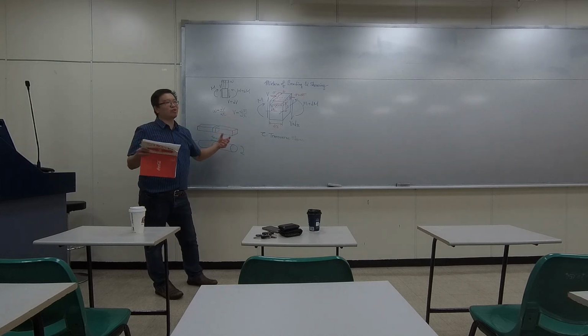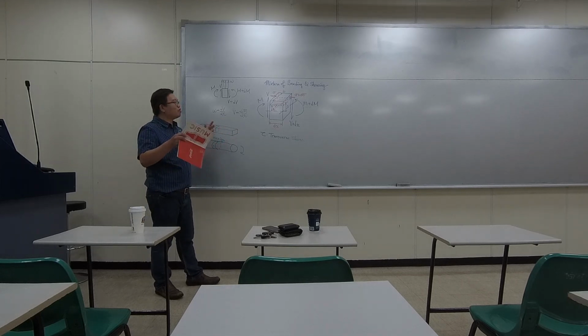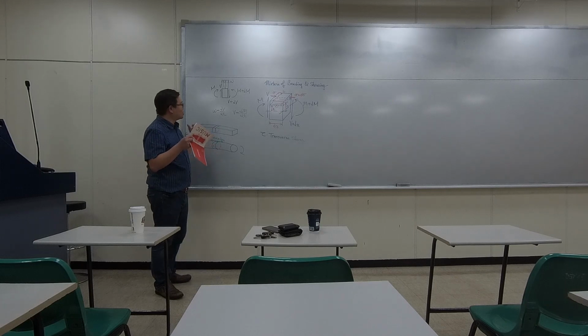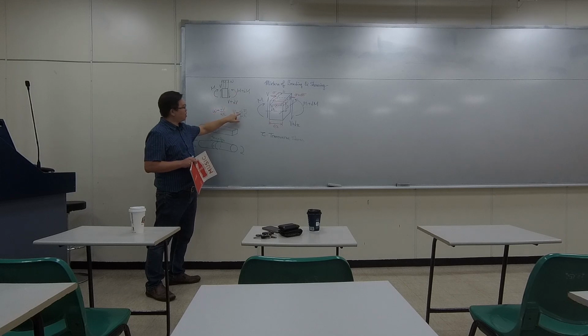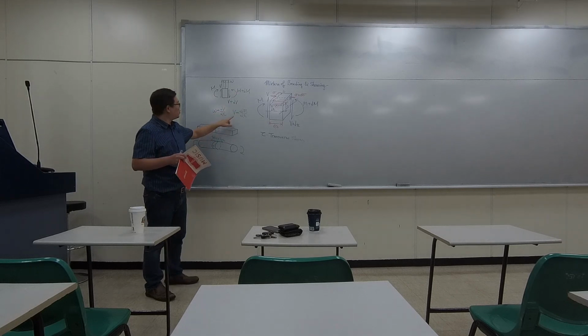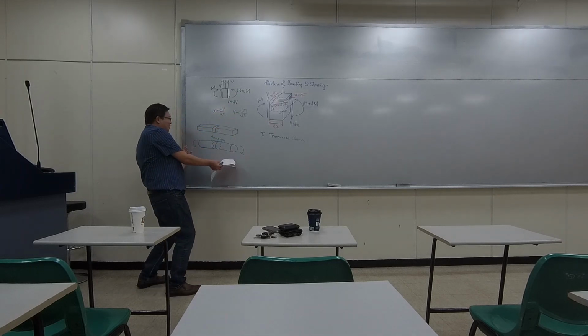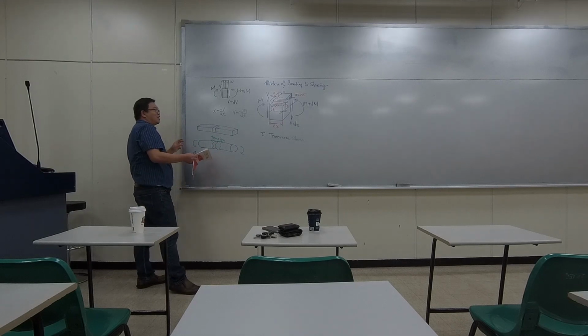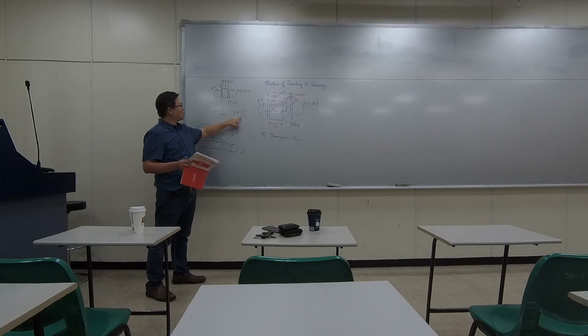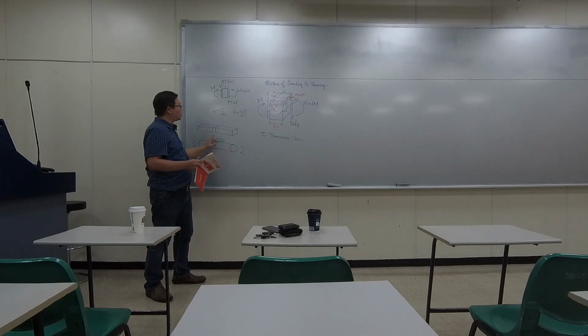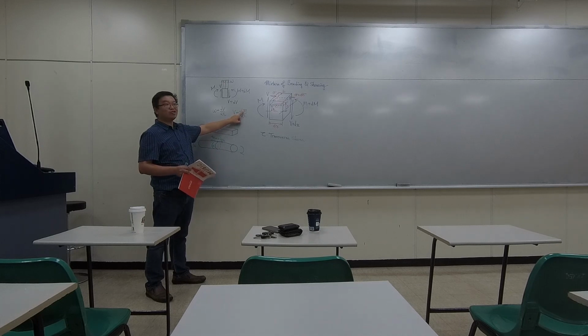Why do people call it pure bending? Pure bending usually is used to describe bending everywhere with a constant value. It's like you bend something and you apply equal bending moment everywhere. When that's the case, no matter where you are, your moment doesn't change, so that doesn't generate a change of your shear.